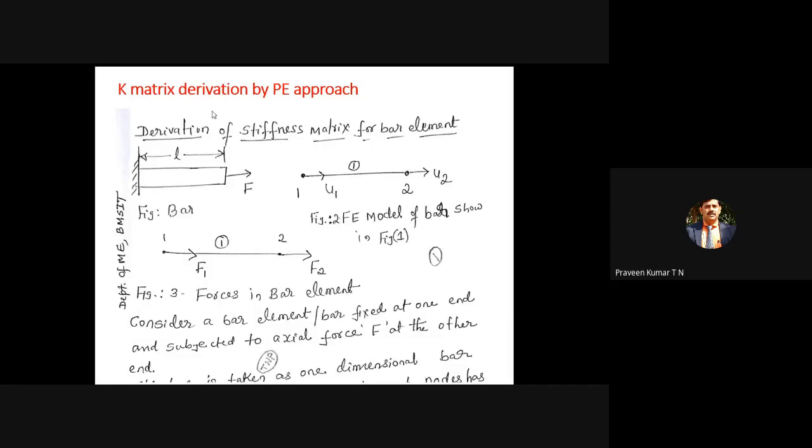Even though we have a physical or mechanical structure like this, still you are putting the displacement at node 1 equal to u1, and the displacement at node 2 equal to u2. In some cases, displacement at node 1 may be 0. In some cases, displacement at node 2 may be 0. When we come to heat transfer analysis, a similar type of element is used, where u is replaced by temperatures. At node 1 the temperature is T1, and at node 2 the temperature is T2.